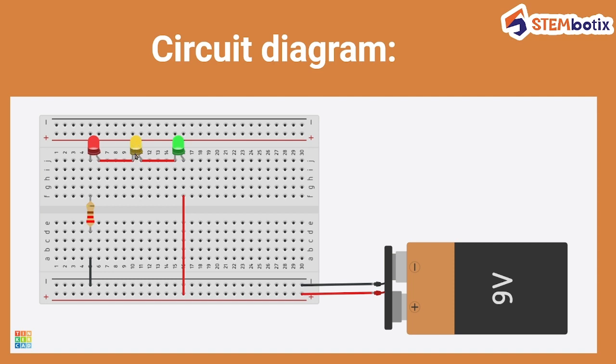see, your current is flowing through this path. Hence, your current has only one path to flow through each and every element. Meaning the current entering from here leaves only here. So there is no alternate path for current to flow through. Hence, this connection is known as series connection. So this is your series connection.